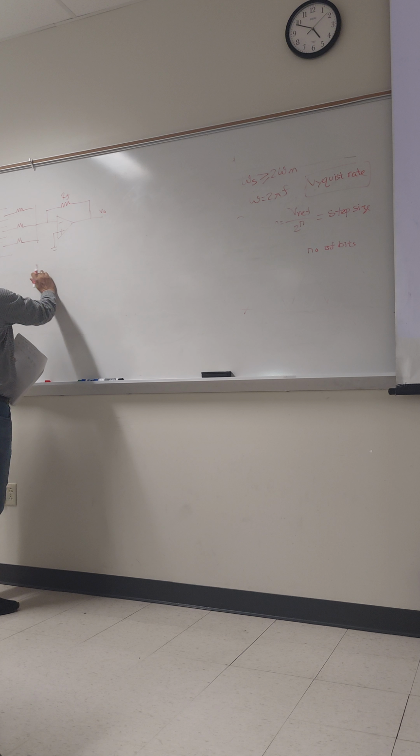This is known as dithering. You can see here. To reduce the quantization error, there are 3 steps we already discussed. One is increasing the ADC resolution, which means you can increase the number of bits. At first we have 3 bits, then we can increase to 4 bits, 5 bits. We can increase the resolution, reduce the step size, and minimize the error. But if you keep increasing your number of bits, the bandwidth will increase. But that is an option. Another option is oversampling. What is oversampling? When you talk about the sampling theorem, there are 2 things. One is undersampling.